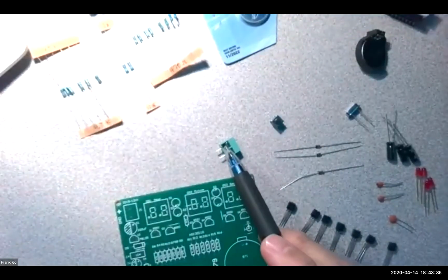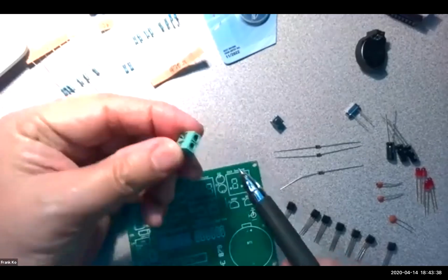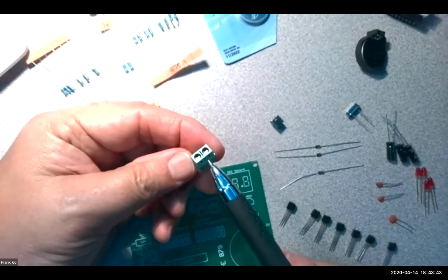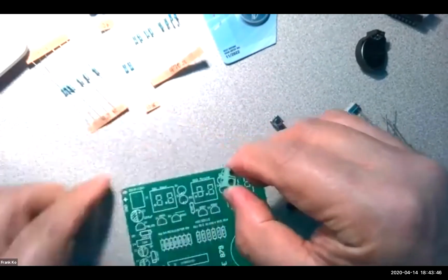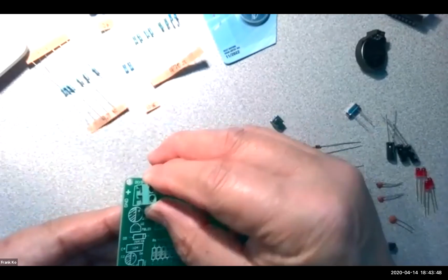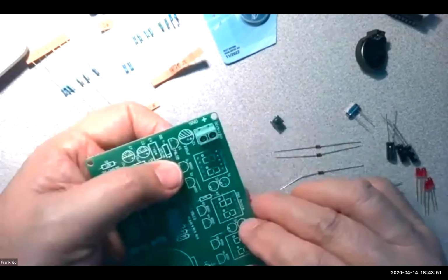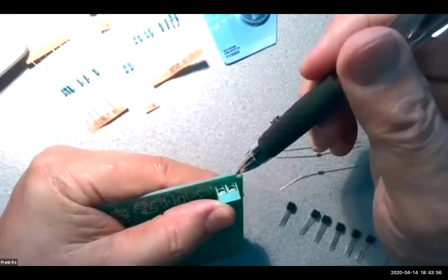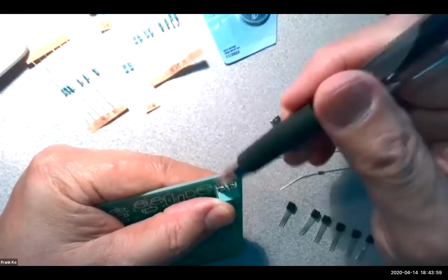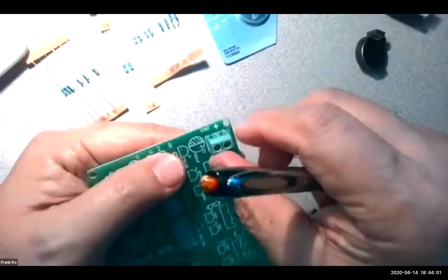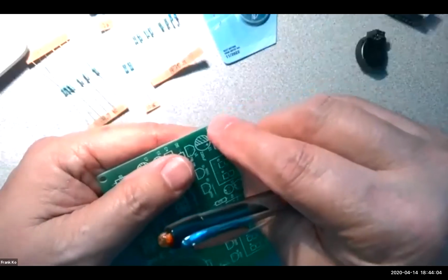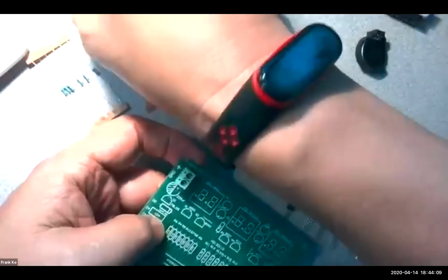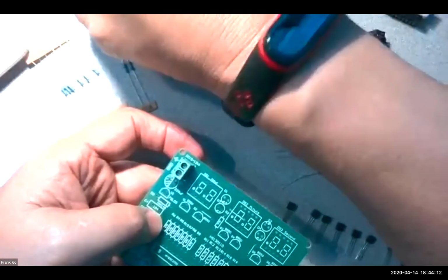There's also, separate from this, this component. This component is a screw terminal, and the screw terminal has your blade type screws right in here, and this is designed to go on this part of the board, like so. When you solder this onto the board, you have to make sure that the access for your wires is from the outside. You don't want to wire this backwards. I've had students do this.